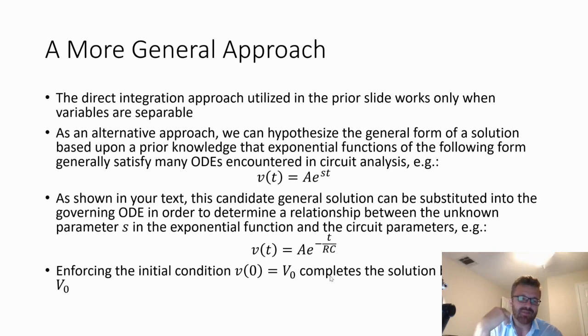So really the more general approach, as I was referring to earlier, is if you notice you have a first order differential equation, because of that property of the exponential functions, you can rely on the fact that the general solution to those equations is typically just going to be an exponential of the form some unknown amplitude A and then some unknown parameter s within the actual argument.